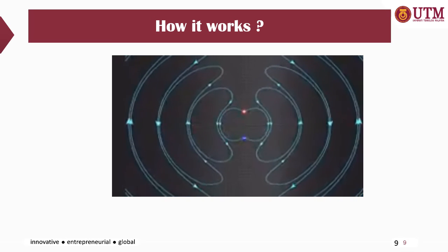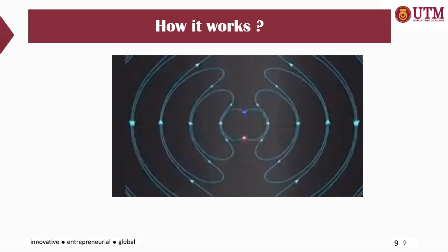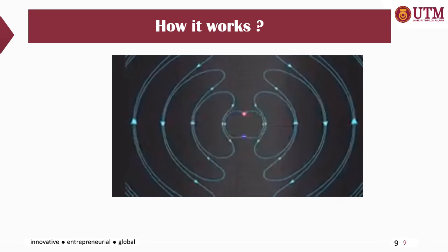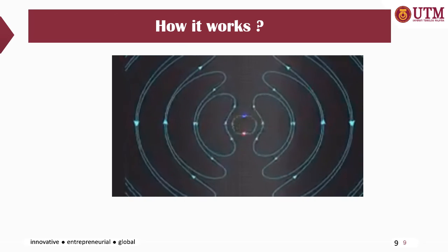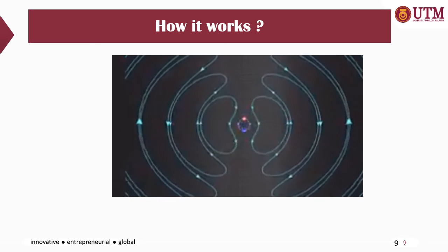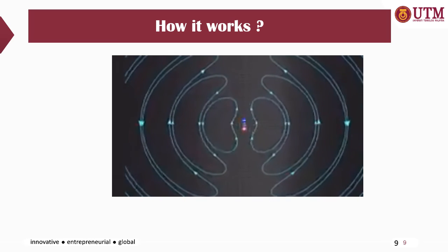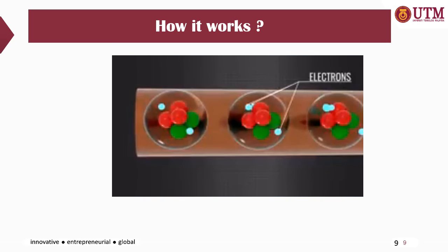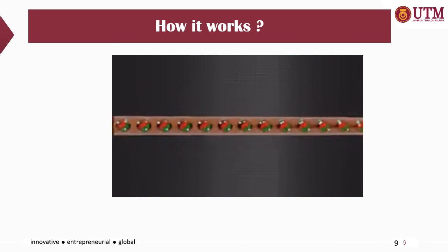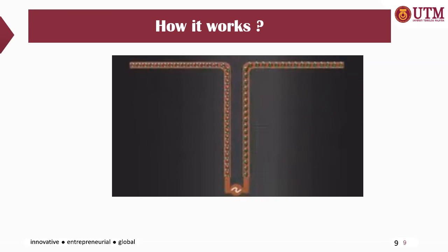In short, we can make an antenna if we can make an arrangement for oscillating the positive and negative charges. In practice, the production of such an oscillating charge is very easy. Take a conducting rod with a bend in its center and apply a voltage signal at the center. Assume this is the signal you have applied, a time-varying voltage signal.